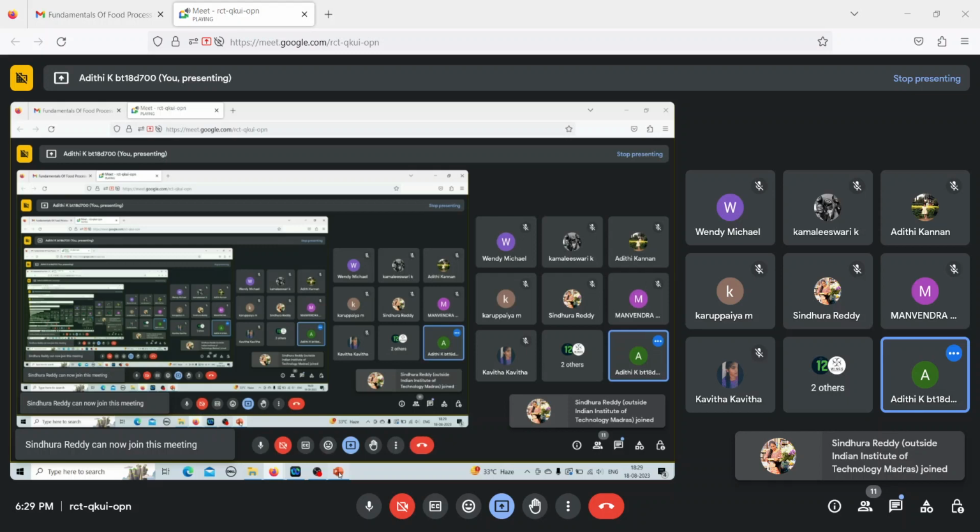Cpl is 3.4 kilojoule per kg, and again T1 is the temperature at which the evaporator is being operated, which was again 323 Kelvin. So 323 minus 273, plus V, which we calculated as 91.384, again in terms of kg per second, into the enthalpy of the vapor, which is 2250. So when you solve all this, we get the flow rate of the steam that is being sent in, which is 0.024 kg per second.